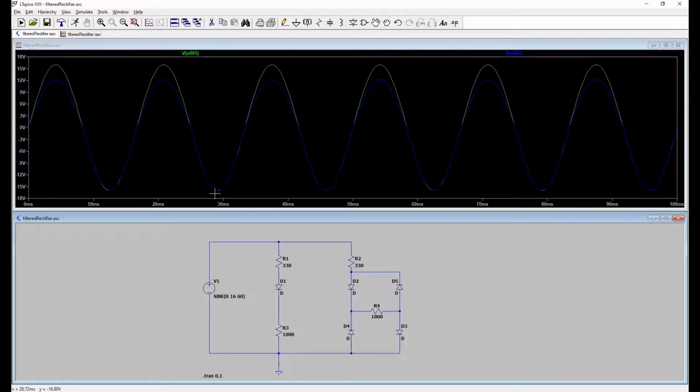And if we do a single click past the diode, then we'll get three traces. One trace being the full supply voltage, one trace being our second click of the input to our rectifier, and the third trace being this voltage across the load resistor. So now you can see that the negative half cycle has been clipped, and the positive half cycle is just a little bit under the input to the rectifier due to the voltage drop on the diode.